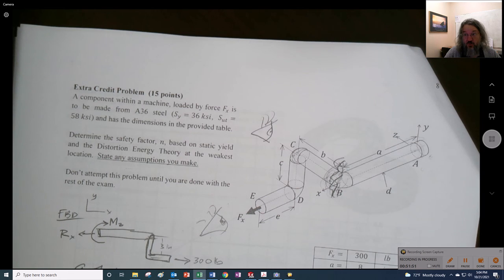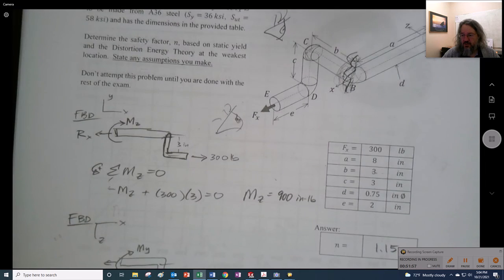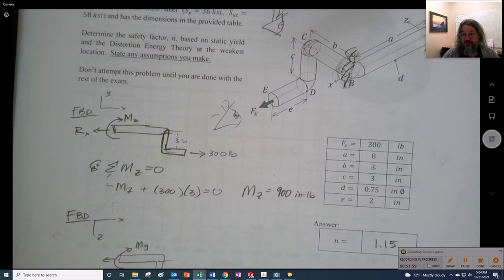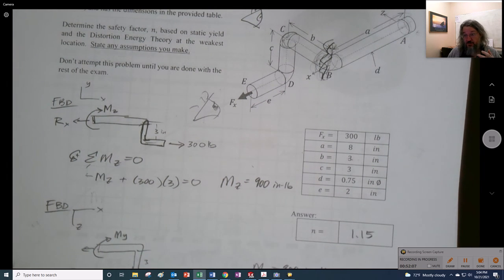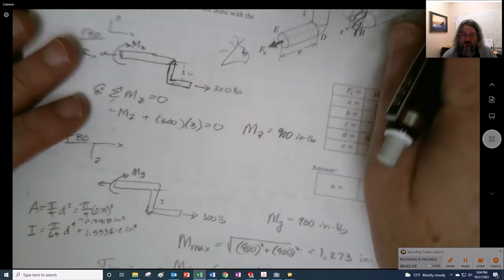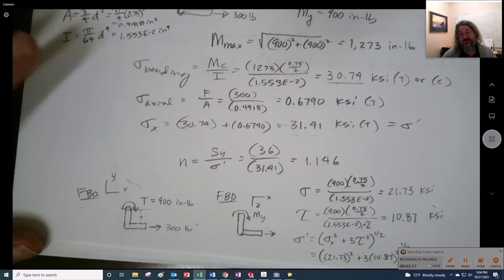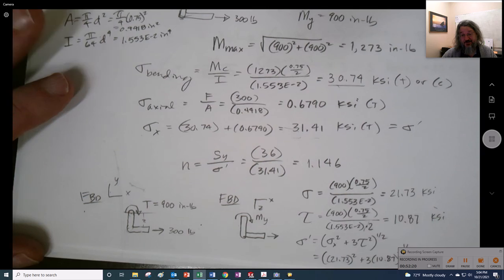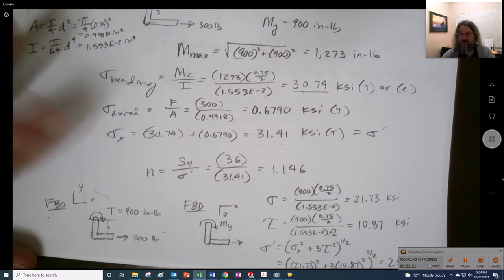But there would be a stress concentration in here at that corner, a stress riser. But we don't count stress concentrations in ductile materials when we're talking about yield, and it's only in brittle materials where we use them. So I think we're okay with our original design, but man, I'd give you some serious bonus points if I saw that you investigated both of those things, because you're a good engineer then. You're really more on the path to being a good engineer, because you're conscientious and looking for all the different things that could possibly happen.